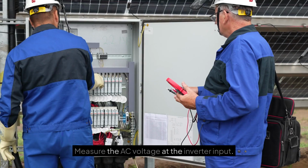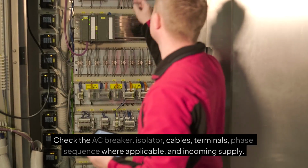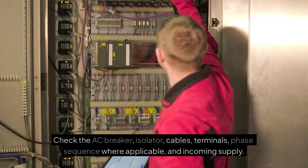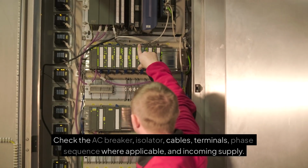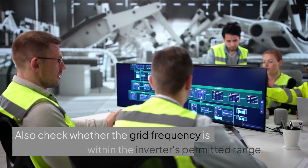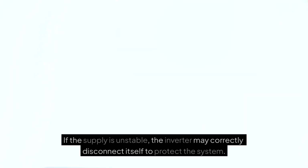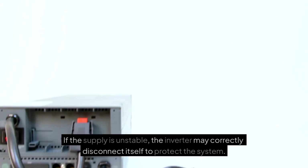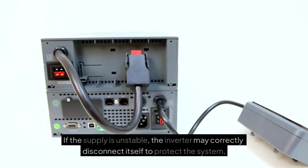Troubleshooting. Measure the AC voltage at the inverter input. Check the AC breaker, isolator, cables, terminals, phase sequence where applicable, and incoming supply. Also check whether the grid frequency is within the inverter's permitted range. If the supply is unstable, the inverter may correctly disconnect itself to protect the system. So, don't automatically conclude that the inverter is faulty.